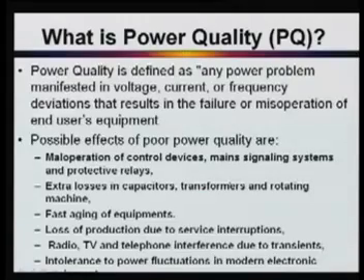The question arises, what is power quality? As per definition, power quality is defined as any problem manifested in the voltage, current or frequency, or a combination of these, that results in the failure or misoperation of end user equipment. So we must always try to provide electricity at the standard voltage, current and frequency.